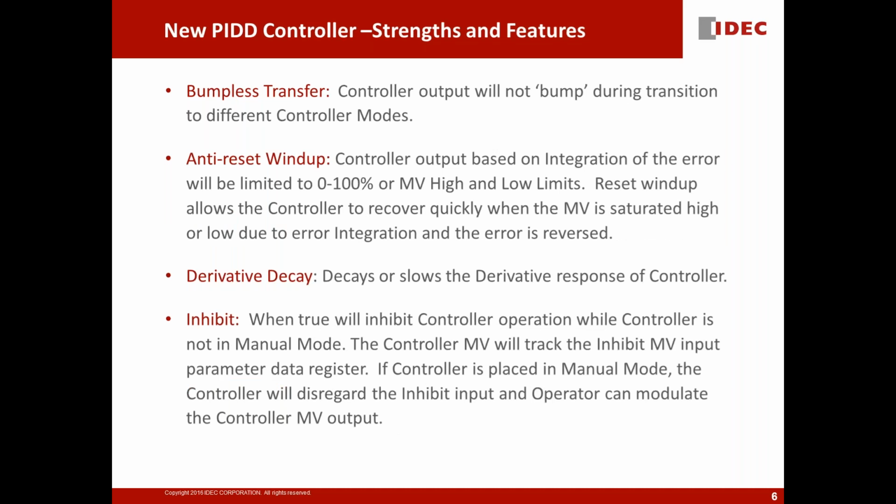This part of PID, guys, of course, has all the bells and whistles of an advanced PID control. It has bumpless transfer, which means the controller output will not bump during transition to a different controller mode. You have the anti-reset windup, very, very important.